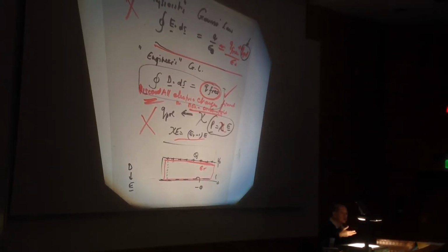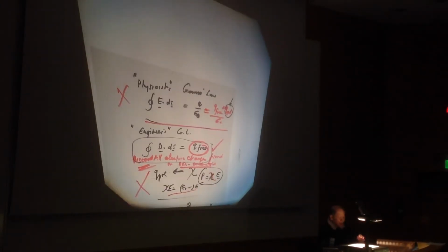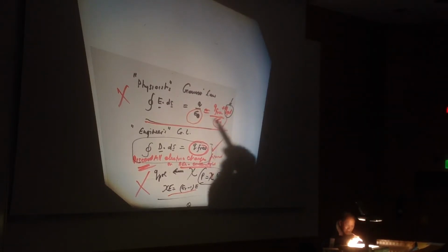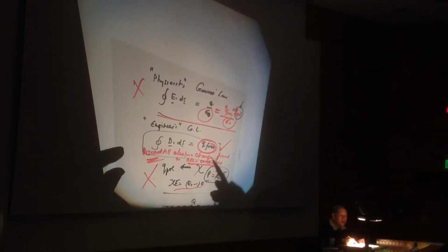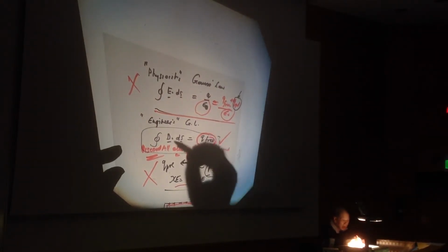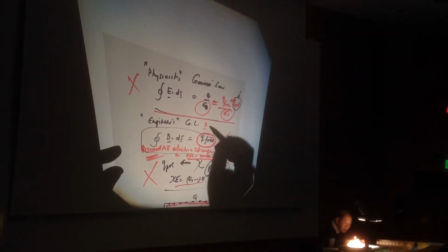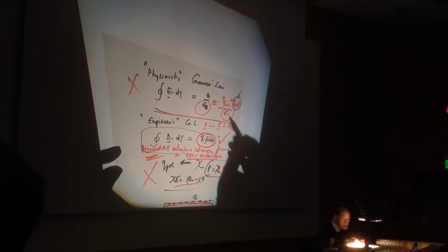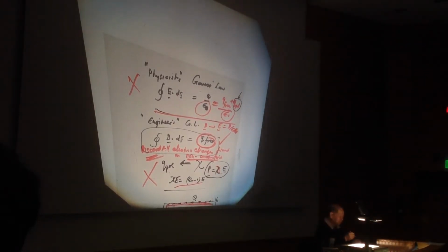So to amplify this, those of you interested can look at books in physics and see how they formulated Gauss's law. They seem to like epsilon naught. But you can see how we engineers do it. They calculate D, and they get E equal to D over epsilon naught epsilon R. The physicist's Gauss's law has no epsilon R. Epsilon R is hidden somewhere here.